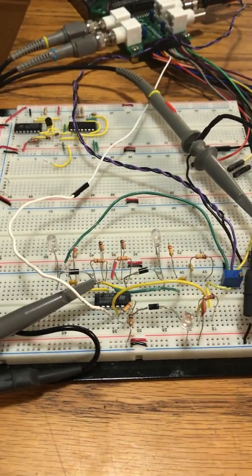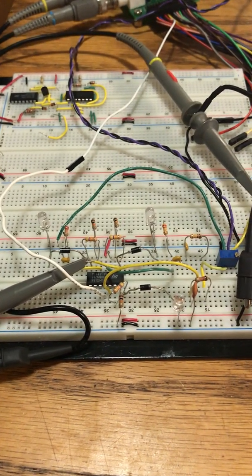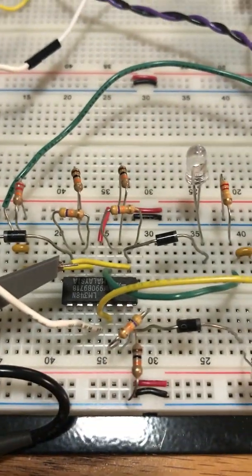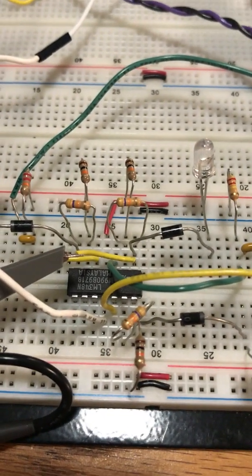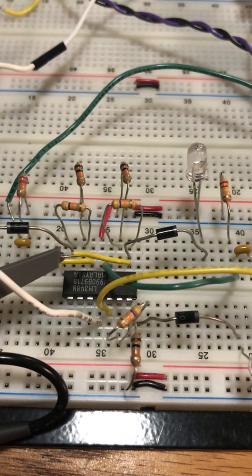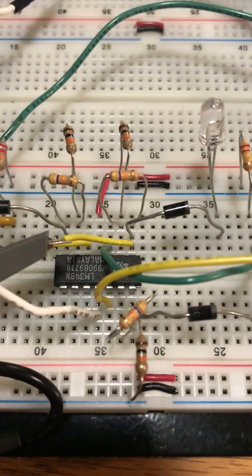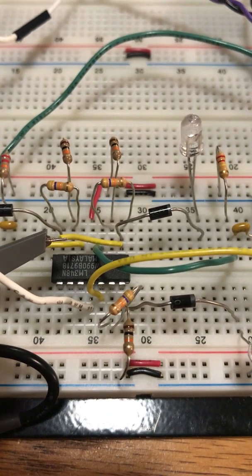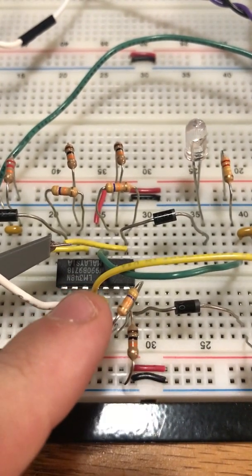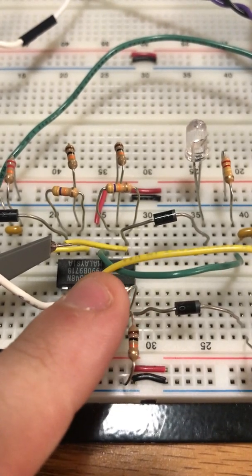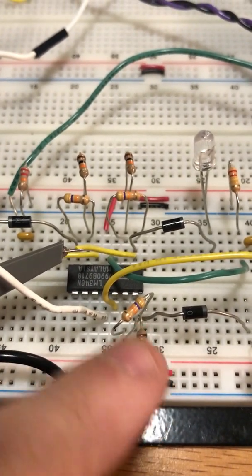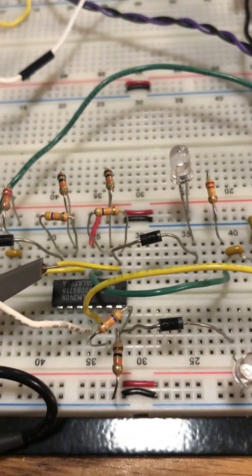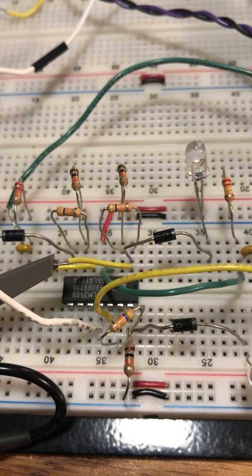And then we just connect them to an op amp, which has a gain of about 5.7 for each of them. We can tweak that, but that's just the value that happened to work for a voltage amplitude of approximately 1 volt that we're using, so that the LEDs light up and dim appropriately. We're working with 10 kiloohms and 47 kiloohms, which for a non-inverting amplifier gives us a gain of 1 plus 47 over 10, which is about 5.7.